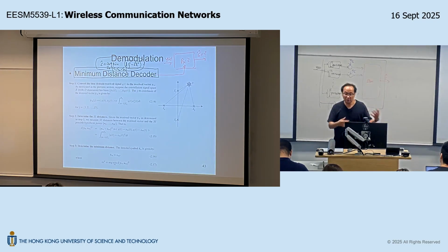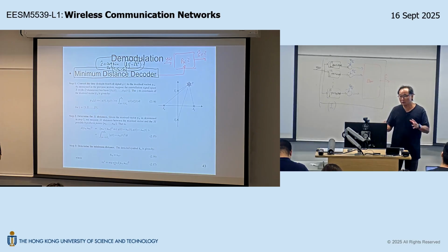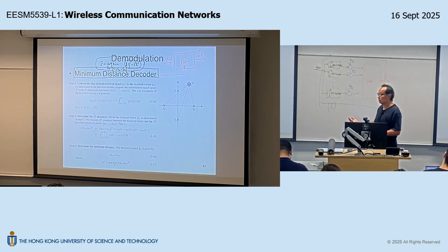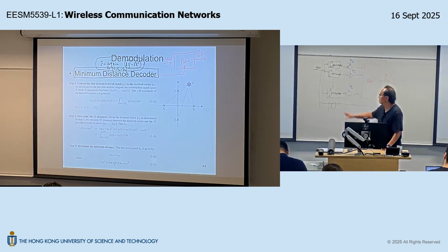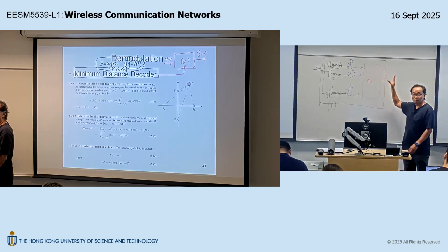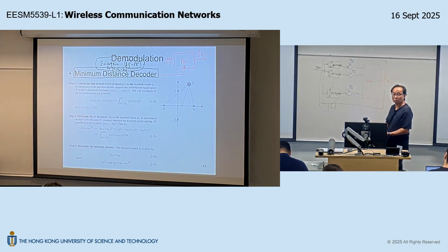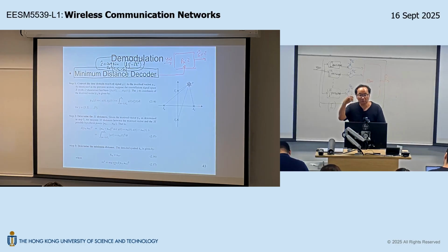And then you figure out some bugs here and there, and then you fix, finally the error probability becomes, let's say 10%, okay? So it seems like it's working. But you do some benchmarking, 10% at this signal to noise ratio is still higher than the normal bit error rate. Okay? In this case, the debugging effort is more involved. You need to figure out which block, which particular module is the contributor to this abnormal error probability performance. And that requires very detailed system level understanding.